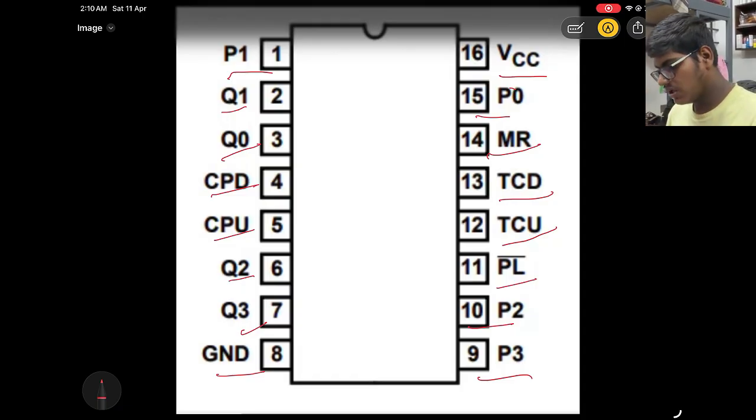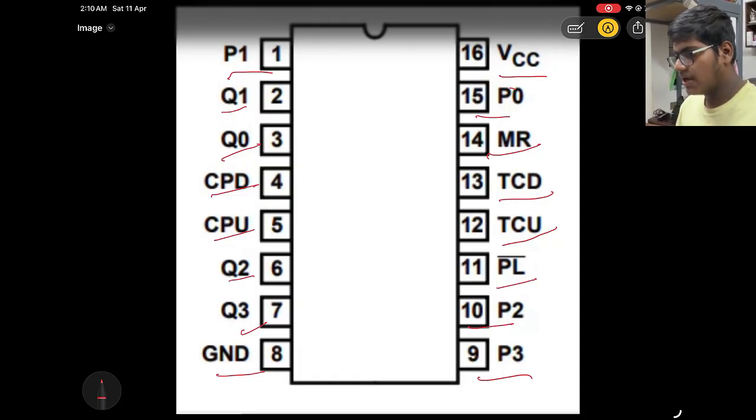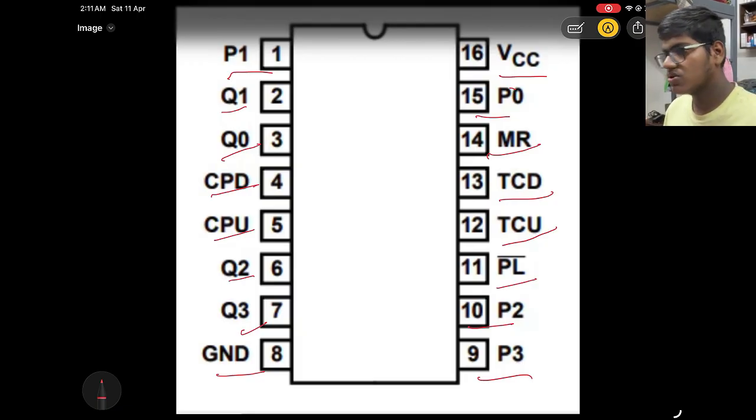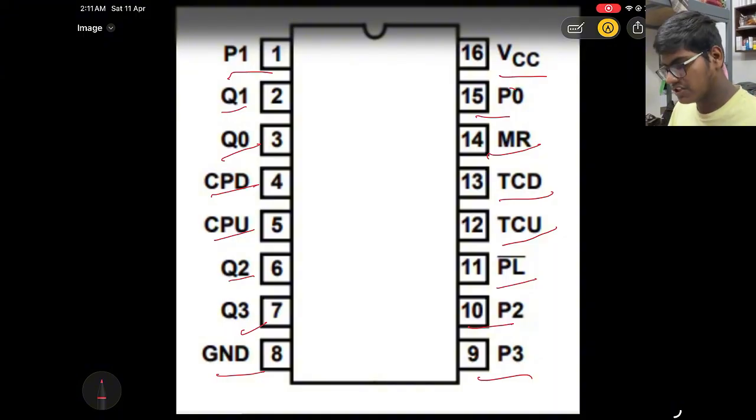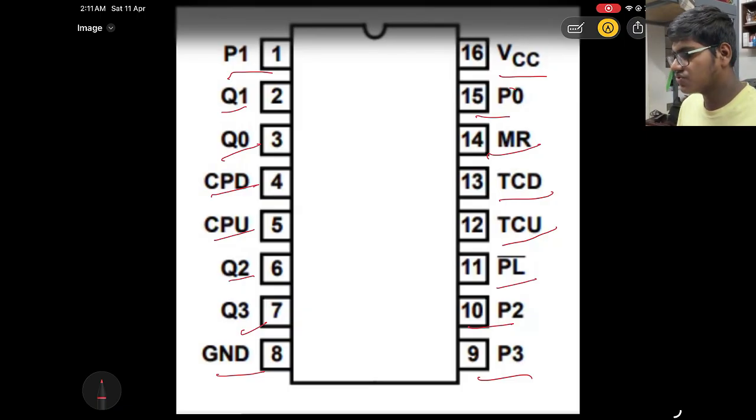the flip-flops toggle one by one and the count is increased. The flip-flops work in the order 0000, 0001, 0010, 0011, 0100. This continues, and when the down pin gets a pulse, this is done in the reverse process. The flip-flops toggle in reverse.